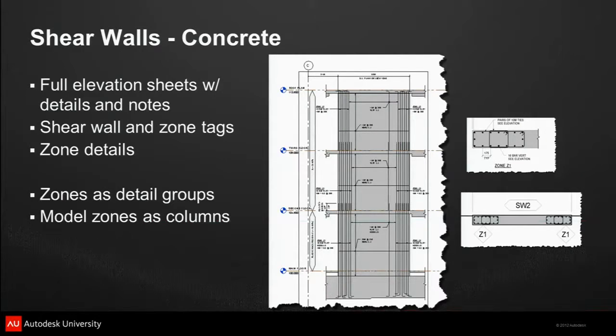Concrete shear walls. We like to tag them in plan. Tag the zones, tag the shear wall, then do details, then do elevations. It's a lot of custom setup. We started by detailing them as groups, but then I couldn't tag them, so I didn't like that method.